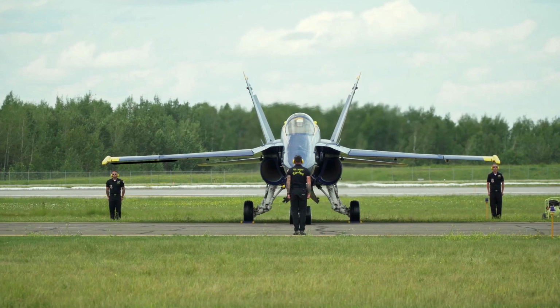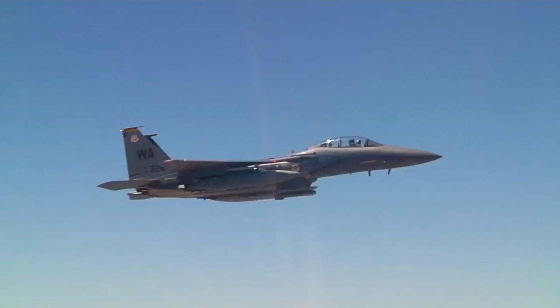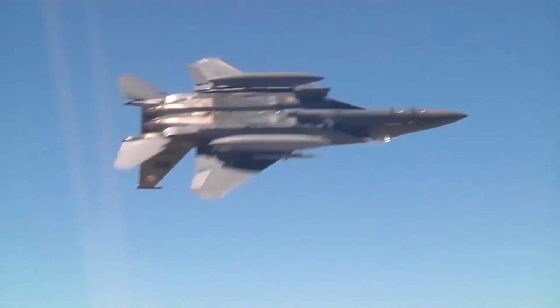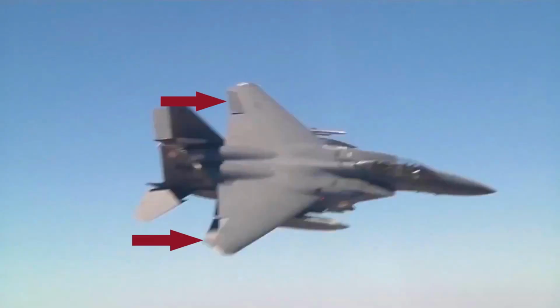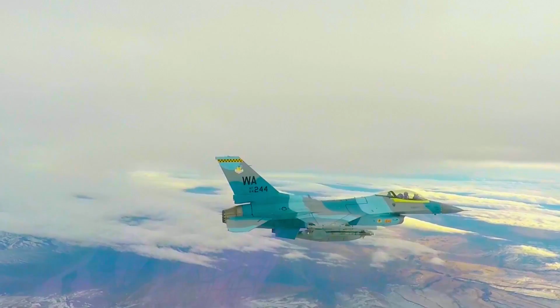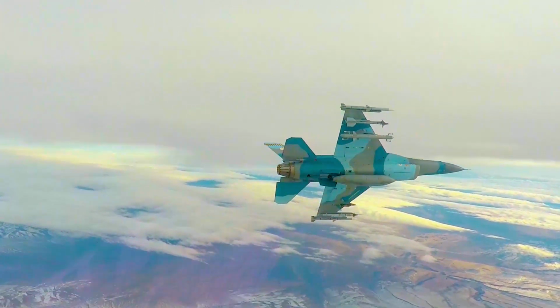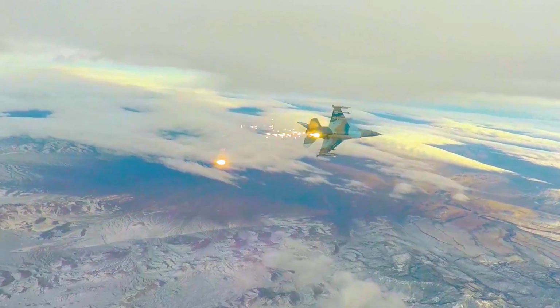So the airstream will push one wing tip upward and the other wing tip downward, and they will turn the aircraft along its longitudinal axis. During turning of the aircraft with the help of the rudder, the aircraft has to bank at the same time.